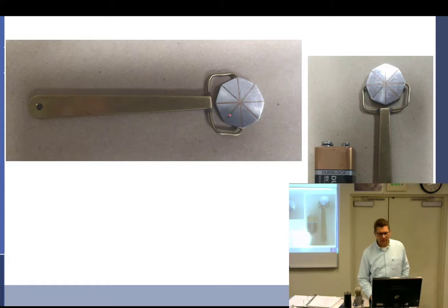Which way would my indications be going? Along the axis. Okay, so I should get one here, and I will. And I'll get one here, and I should get one there. How about here? Not going to get anything. So if I get these showing up, I'm good. I'm getting some magnetism through the machine that would at least pick up that kind of discontinuity.